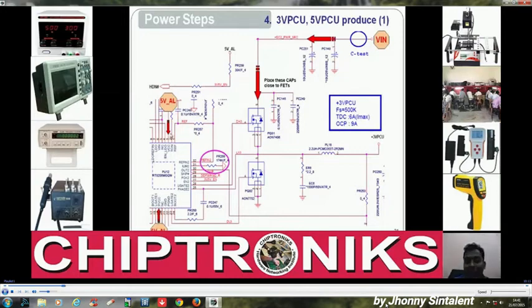So this 5V_L is very important because it gets fed to VCC. VCC supplies power to the internal logic of this regulator IC, whereas PVCC supplies the driver circuit which generates the signal to the low gate MOSFET, right?